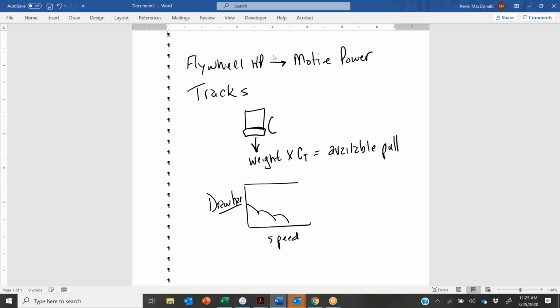And so we would take our vehicle production, how much work we're doing, what our load is, and we come over to this gear and see how much drawbar pull we had and at what speed. And that's how we did dozers, and that's how you do all tracked vehicles. But rubber tires are more complicated.